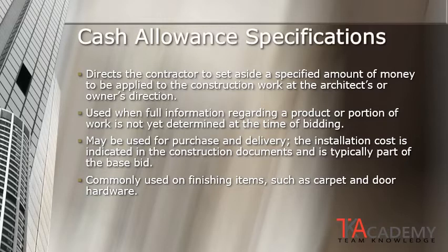Flooring, if the flooring is going to be replaced, we know that the concrete slab may be old and worn, cracked, may need some patching or leveling, but we don't know the extent of that until the existing flooring is removed. Therefore, we would use a cash allowance, set aside that certain amount of money for the purpose of patching and repairing of the floor before the new floor system is installed.